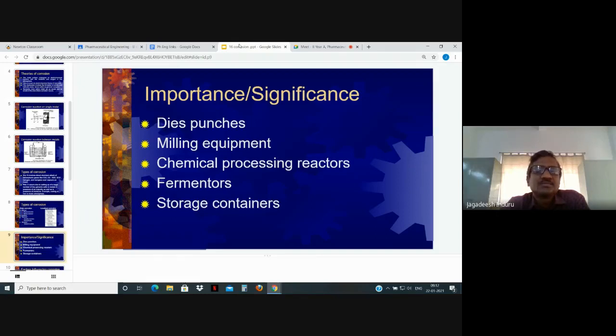We know that oxygen is more prone to give corrosion effects. Similarly, most of the time your product is going to be inoculated with some microorganisms. We have already seen microbial corrosion, where microorganisms are able to convert the product into inactive species into the active and electrolyte. So they create a more corrosion-prone environment, and in those cases also we are going to have this corrosion problem. Most of the time we are using glass-lined vessels, so that we prevent exposure of these media for the longer period of incubation by putting a glass coating over that.